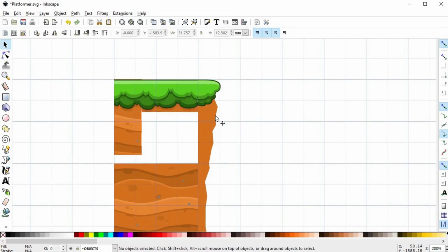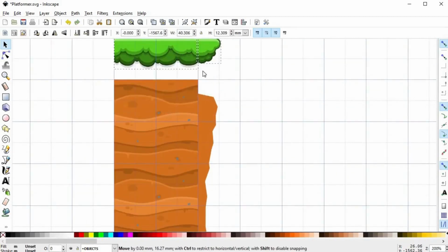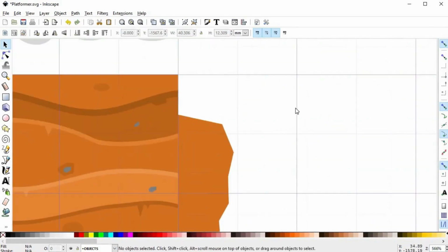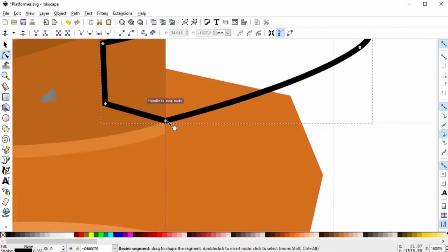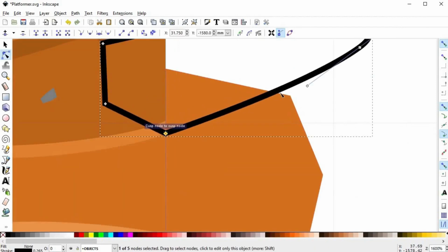As far as the details, of course, the first thing we should do is to continue with the wavy shapes. This is easy, just enable snapping, with the grid snapping disabled, and with the pen tool snap to one of the corners of the shape and finish it off. I'm just using a single shape here, because this shape is really simple, so I leave the silhouette and finish it off in one go.